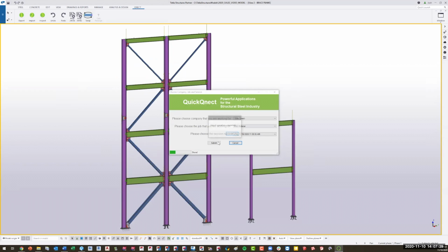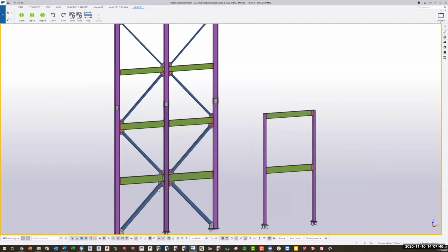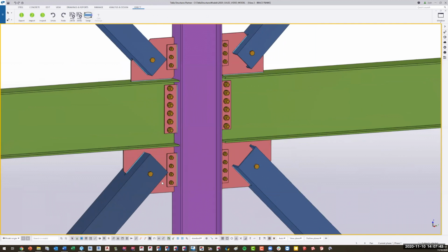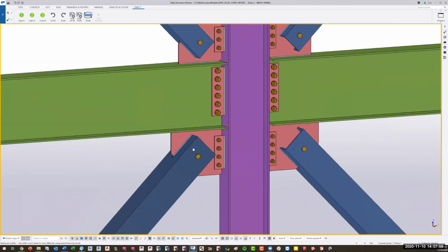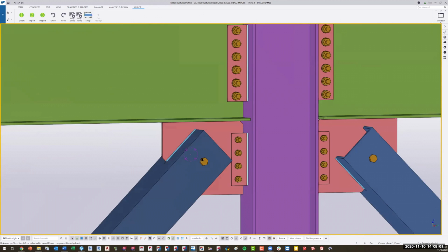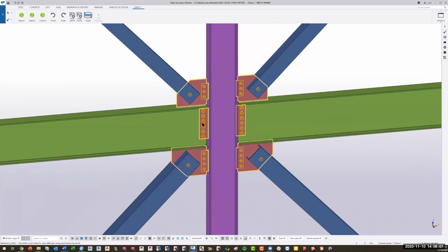You're going to have not only the complexity that comes along with it, but you're also going to have the ability to look at the calculations, because they now live and breathe within these connections. Everything that's in here is 100% modeled. You're going to see all the welds, all the bolts, the holes. For instance, you're going to see this is a through bolt as an A307 for erection purposes, nothing more than that. You have your slotted holes, your shop welds versus field welds, and so on. Getting into more of the meat of this connection, you'll see this is the entire component.